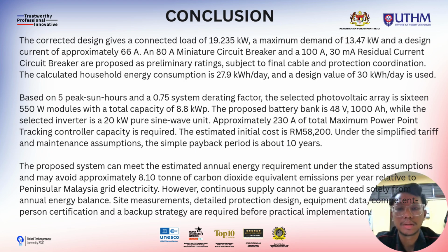For the conclusion, the corrected electrical design features a connected load of 90.24 kilowatt, a maximum demand of 30.47 kilowatt, and a design current of approximately 66 amp, which will be protected by an 80 amp MCB and a 100 amp 30 milliamp RCCB to support a daily design consumption of 30 kilowatt hours.